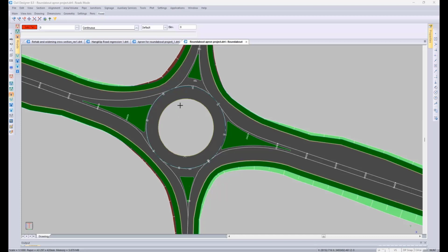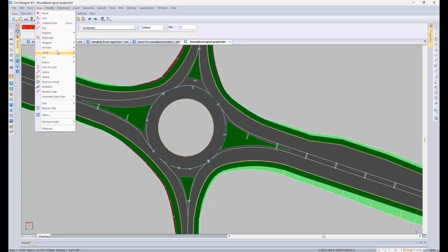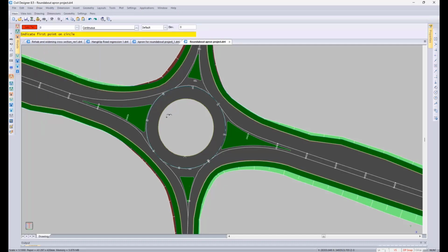So just bear with me, let's go to CAD, I just want to check what the diameter is of this circular right road edge string. So I'm just going to draw a circle through 3 points. So there is a road string entity, so I can do an end jump. That's my first point there. Do another end jump to there.